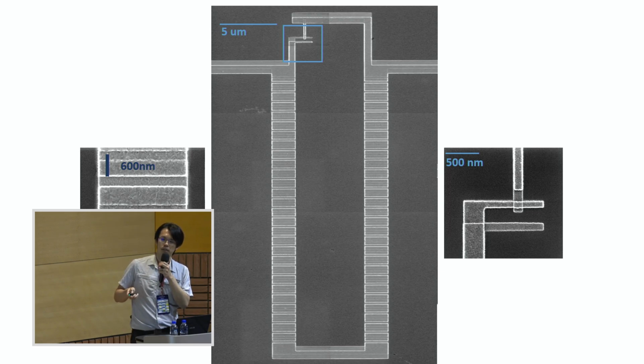A lot of people are afraid of this kind of Josephson junction array because the fabrication looks very, very hard. But actually, as long as you have good parameters for making these Dolan bridges, the yield rate of these Josephson junctions is quite high. So it's not that hard. And this is the small Josephson junction that we made in here.